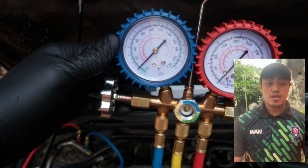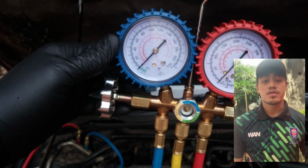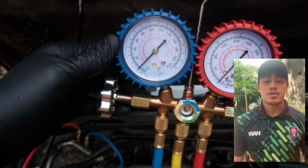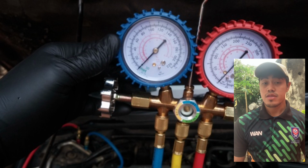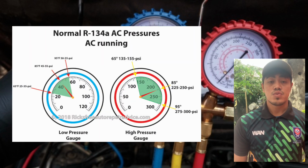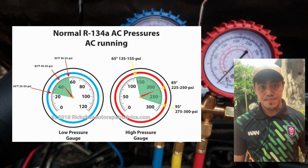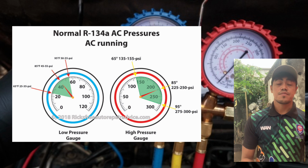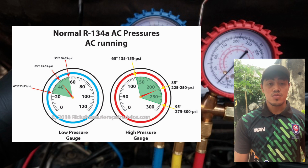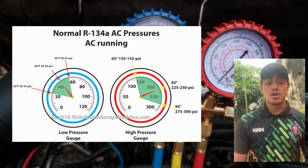Okay, after connecting, open them by turning the knob clockwise until they stop, and then observe and record the pressure at the manifold gauge. But take note, if the pressure is less than 85 to 95 psi, please add the refrigerant to the system. But if the pressure is far below that value, maybe the system must be checked